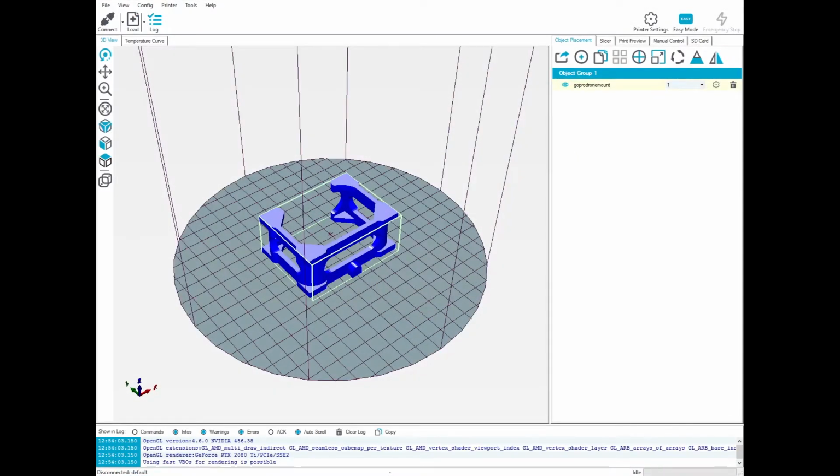The next step to 3D print a custom object is to slice this object. You're going to turn this 3D STL file into a series of layers that the 3D printer can just follow the G-code properly to print out plastic in the right areas, to move the print heads into the proper places. You're going to turn this into the universal CNC machine language called G-code, and 3D printers use a reduced set of G-codes. They don't have the full set available in most of the print firmwares, but it's plenty enough to do 3D printing with.